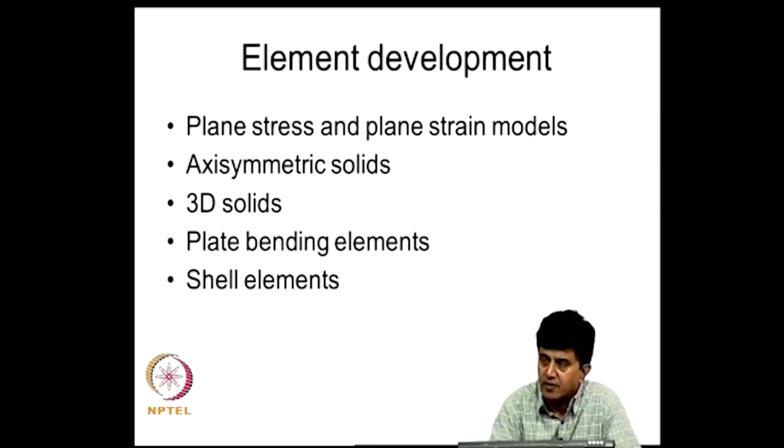The general template for achieving this is basically to write the appropriate equations for strain energy and kinetic energy, identify the field variables, take an element, identify the nodes and degrees of freedom, represent the field variables using polynomials in terms of the nodal degrees of freedom, substitute into the Lagrange equation and derive the equation for the nodal degrees of freedom.